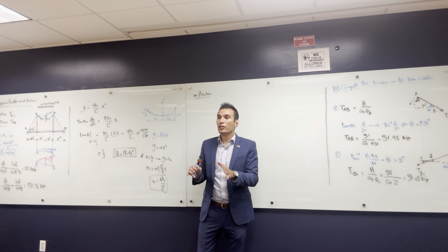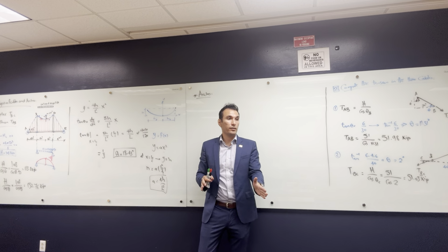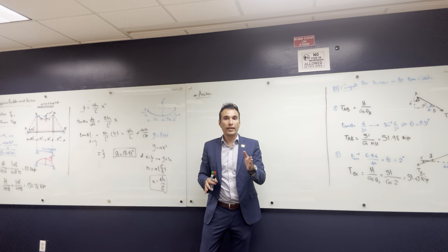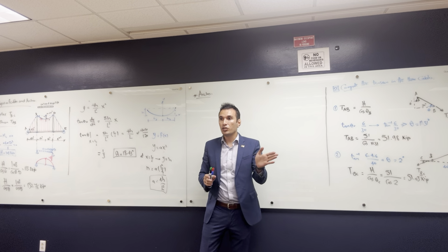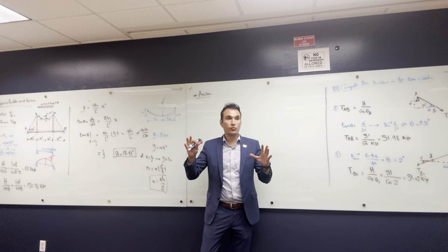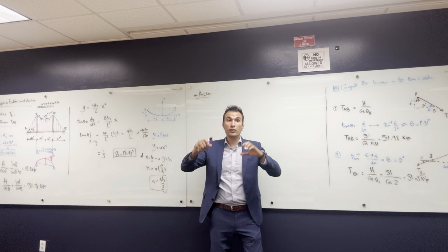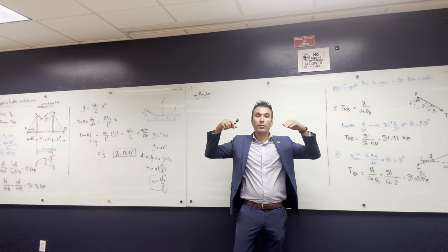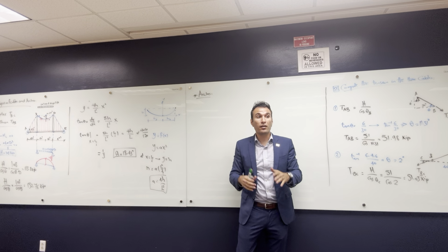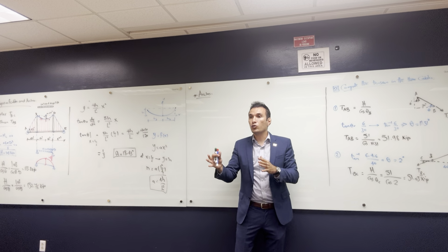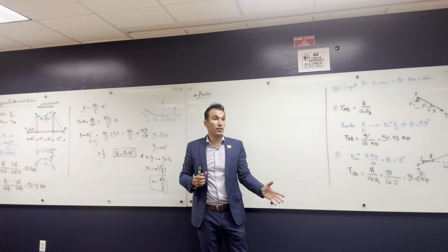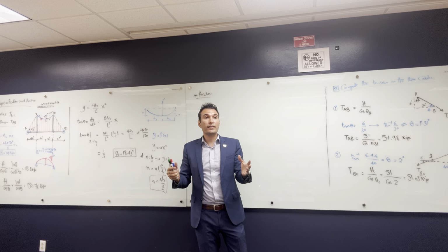And as a structural engineer, our enemy is the bending moment. Bending moment is like a snake. It's not tension, it's not compression, it's like trying to transform between these. So it puts compression in your cross section from the top, and then you will have tension in the bottom. So you have to face it in 2 ways. You have to use concrete and you have to use steel. Okay? So it's like a snake.